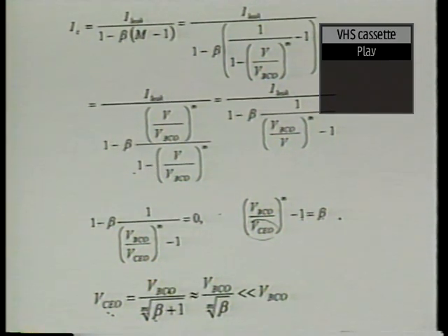Okay, but usually beta is not quite 100 because breakdown happens when the current is still not very large. 1 microamp maybe it's already breakdown. At 1 microamp beta might have not reached the peak value, might have actually. So therefore, the transistor breakdown voltage is significantly lower than the base collector junction breakdown voltage.